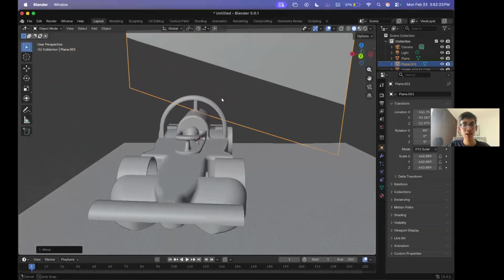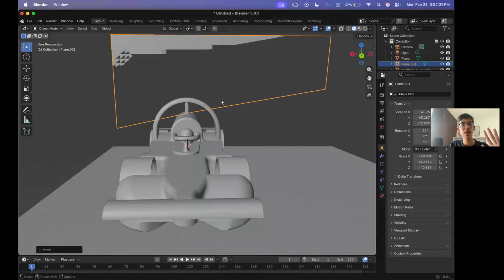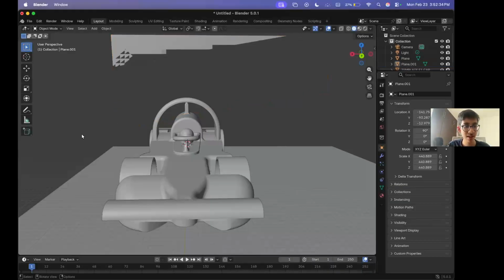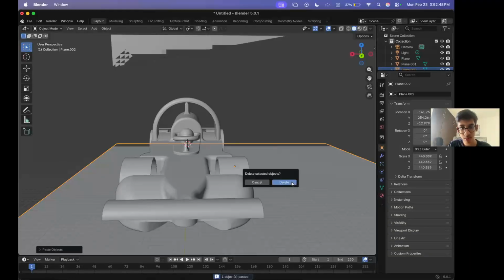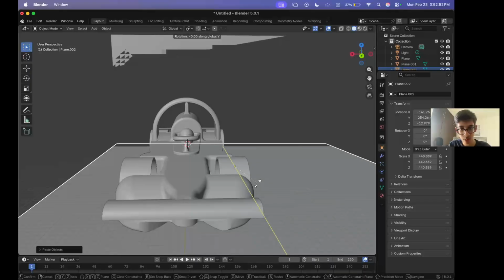We want the light to come from one direction, not two. So we're gonna put 3 planes, one at the bottom, one behind the car, and one on the side of the car. So let's add another plane. Let's press Command C, Command V. Let's press R. Let's press Y and then 90 degrees.